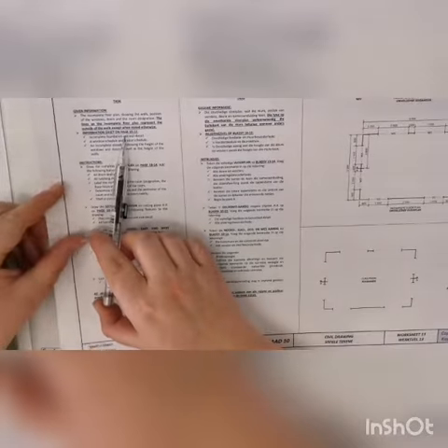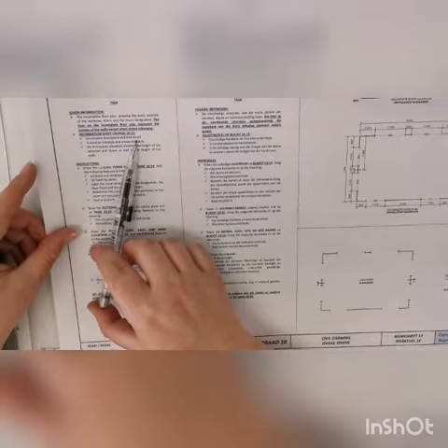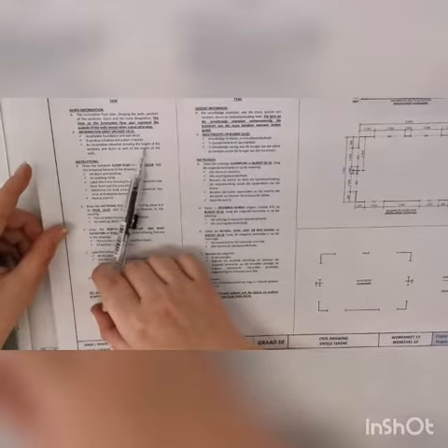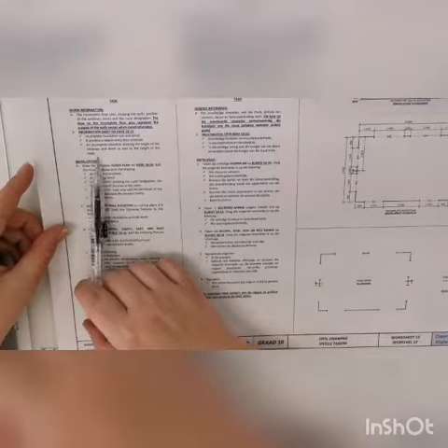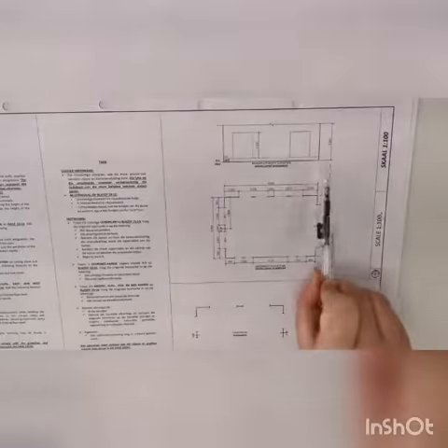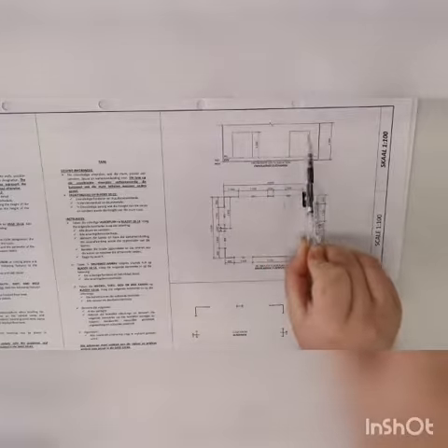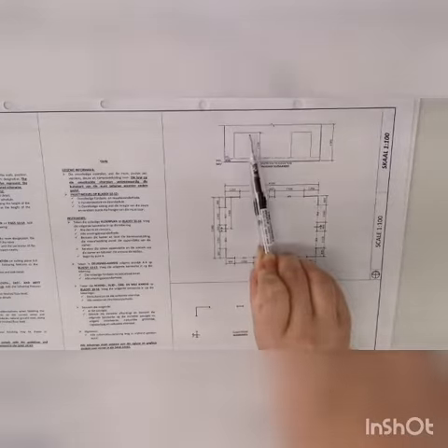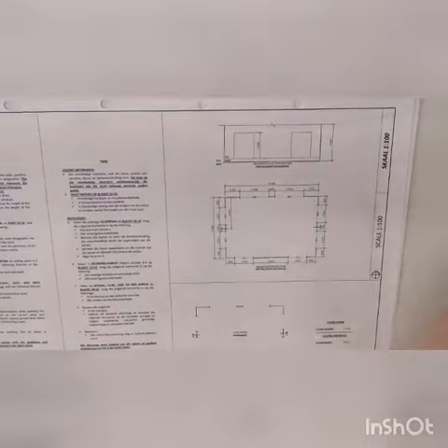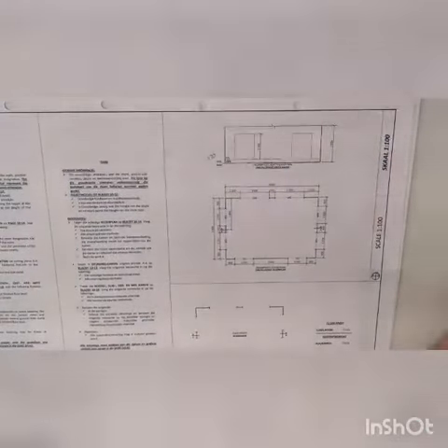Then you're also given an information sheet, which will also be given in an exam. You're given an incomplete foundation and wall detail, a window schedule and door schedule, an incomplete elevation showing the height of the windows and doors, as well as the height of the walls. For this one, they've given you the specific heights that they want from the natural ground line to the top of the wall, as well as from the finished floor level to the top of any doors or windows. What is the measurement here between NGL and FFL? It will always be the 170 unless they state otherwise.